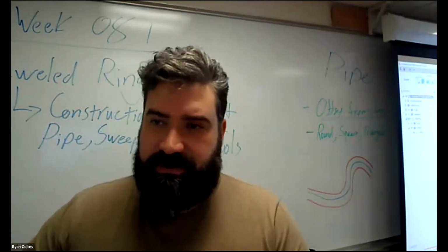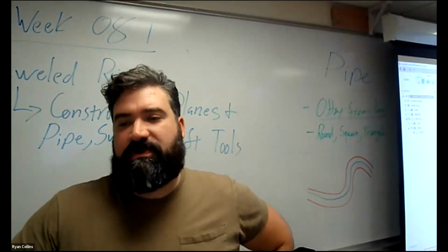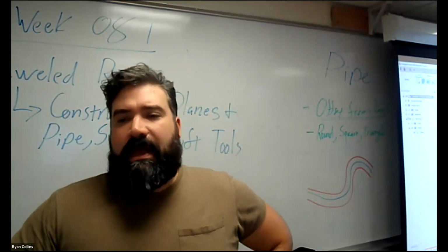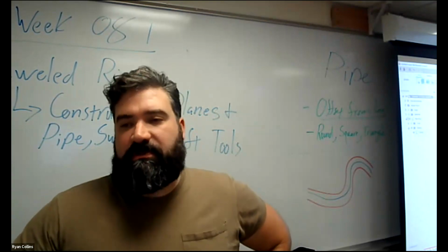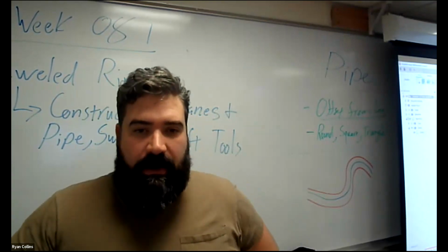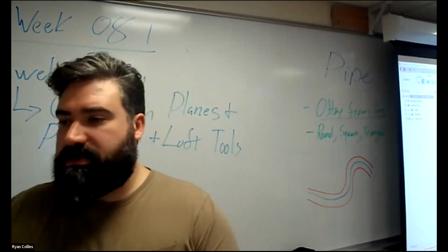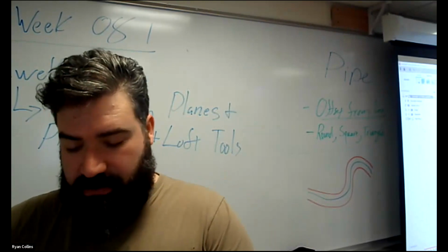Okay, so that's a different method for using the pipe tool. So that totally works. Making multiple pipes, join them together. And I'm going to show you how to create a setting and such. All right. Another option would be making a sweep or using a sweep.